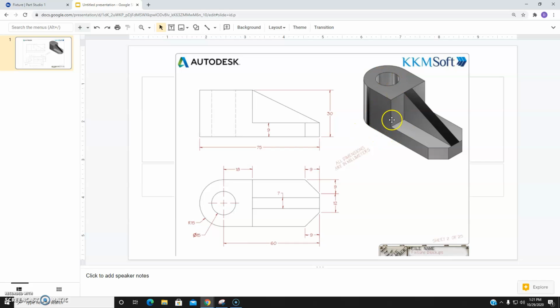And we've got this riser, this boss that comes up, okay? That's kind of like a half rounded, half straight cut off piece, so that's 2. We've got this web here for support, this triangular piece. And we've got our hole that goes all the way through. If we look at our 2 views on our drawing here, we've got our top view and our side view here. So we're going to start off by drawing out basically this entire base, minus all the internal stuff. So no hole, no line that goes across, no web lines, just the very basic outside. And then we will extrude that up 9 millimeters.